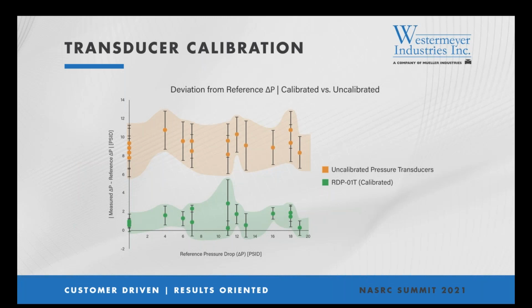In addition, by observing the average values and their corresponding error bars for the 2 different cases, uncalibrated versus calibrated, it is clear that the results are statistically significant, given that we're looking at 2 very distinct data clusters. But that is not the case when we're looking at each data set individually, where multiple separator inlet pressures are utilized. This all means that the results are not dependent on separator inlet pressures, and the accuracy trends shown in both graphs presented so far are expected to remain the same outside the range of separator inlet pressures explored in our experiments.